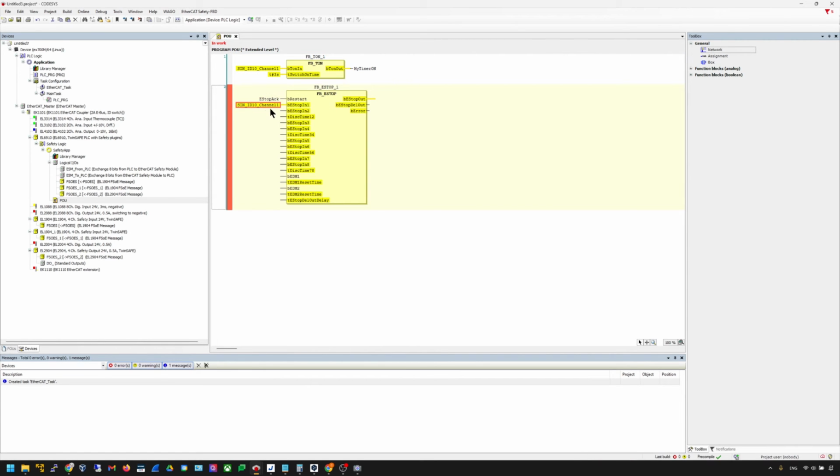Okay, then for here I'll just copy this signal. Actually no need for all, but because this is a tutorial, I would like to show you all the parameters in here. So I just copy to 4, here's 4, and then I have 5, 6, 7, and 8. Great. And then here is the feedback. BEDM is the feedback. Actually, I didn't connect the feedback in this tutorial, so I just directly copy my safety output in here.